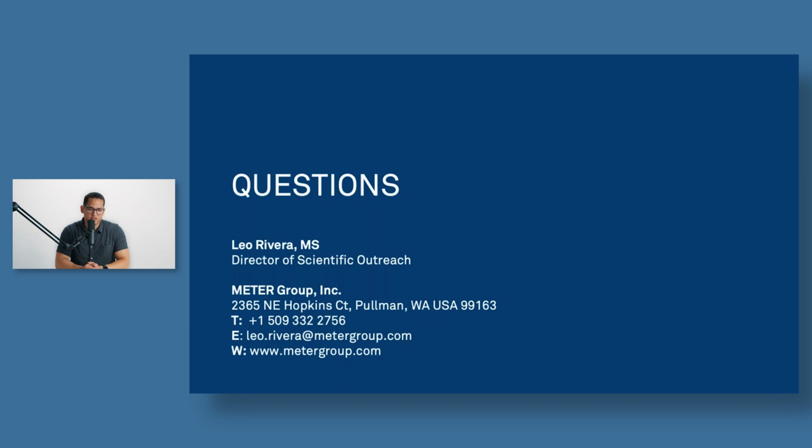Yeah, that's a really good question as well. And I think it depends on whether you're seeing a wetting event coming through or you're on the drying curve. What we typically see when it's in equilibrium with the soil and the soil is drying, the ceramic actually behaves at about the same rate of change as the soil in most situations because it has a fairly similar hydraulic conductivity. And so when you're drying, it actually responds just like the soil changes. So I'm not really concerned with your frequency there. You can have that 10-minute frequency or higher if you wanted to, although things don't change that quickly.